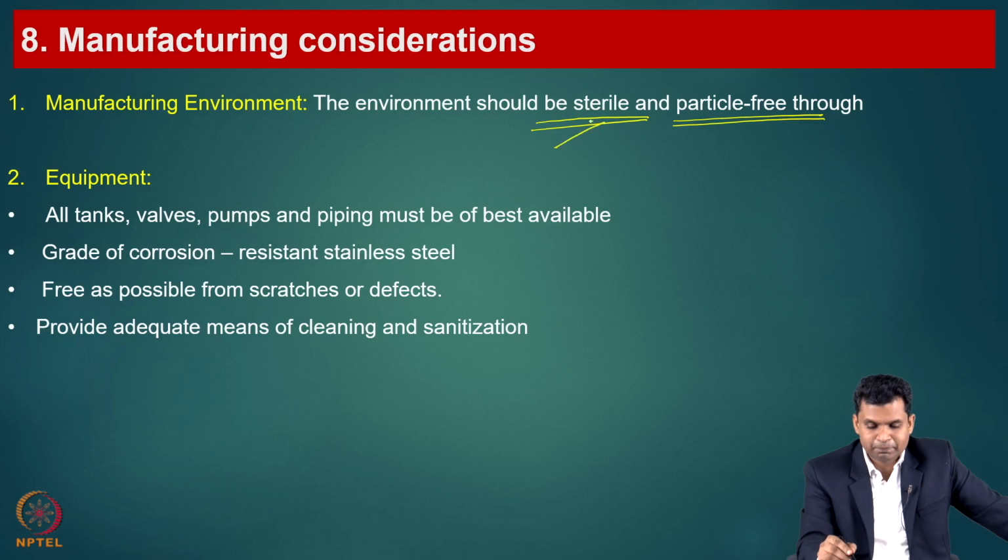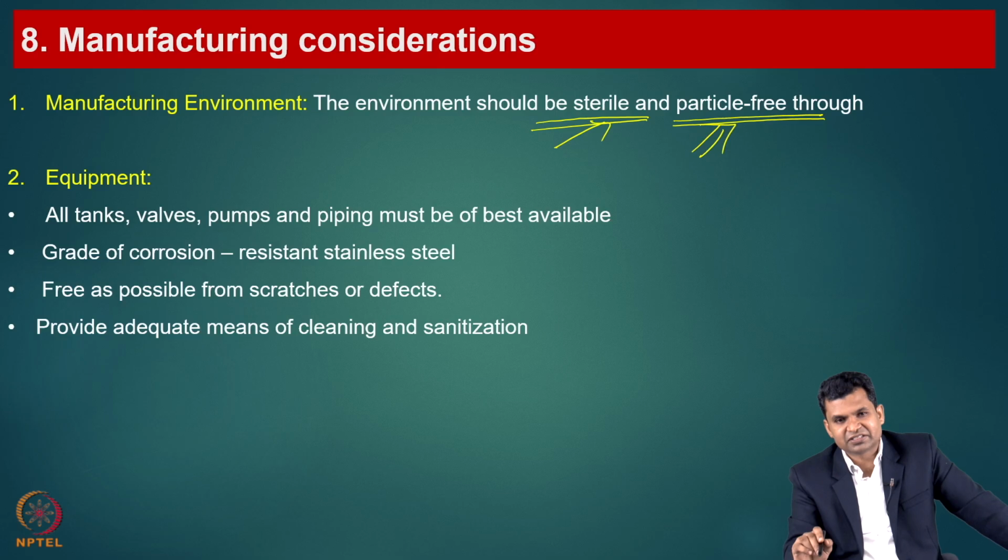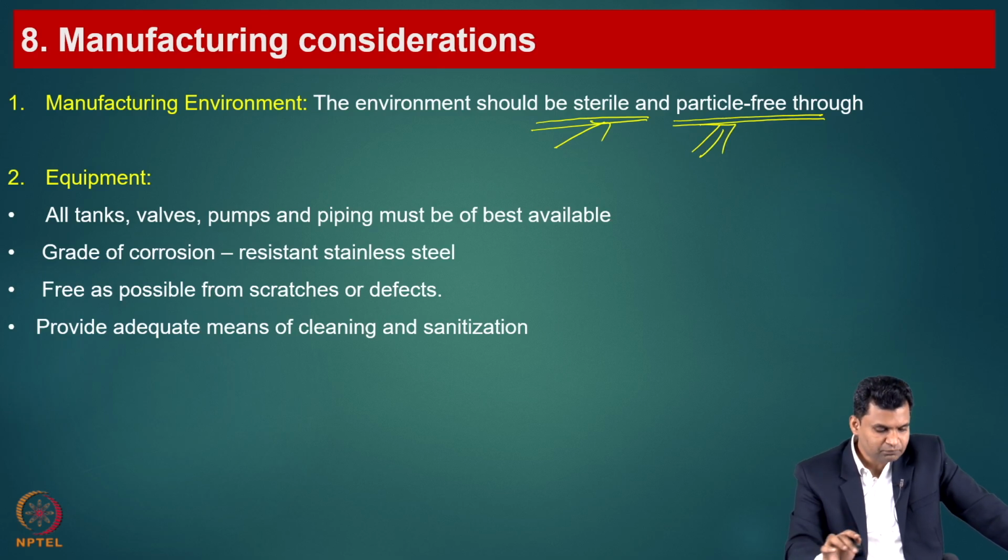Here we can perform various sterilization techniques. By using clean rooms, we can maintain the sterility in the environment, and by providing various biosafety cabinets, and also we can use laminar air flows and HEPA filters. With that we can maintain the manufacturing environment clean, sterile, and particle free, and that needs to be maintained regularly.